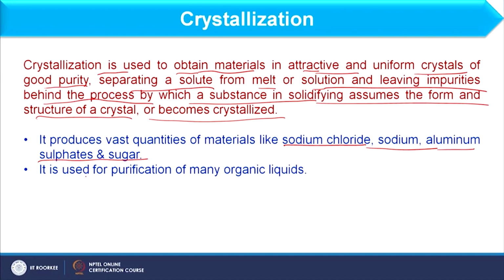When we have the evaporation, we get a solution with high concentration, and that concentration is sufficient to be used in a crystallizer. Usually in the sugar industry, or we can say the sodium chloride industry, we consider the crystallizer as the main unit. And secondly, we can consider crystallization as a purification of many organic liquids. When we purify an organic liquid, how do we remove the impurity? That is done through crystallization.